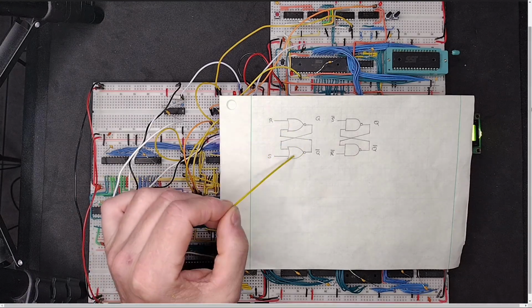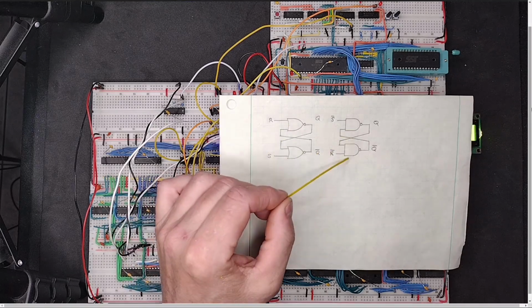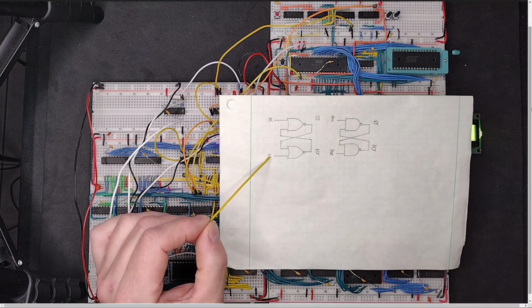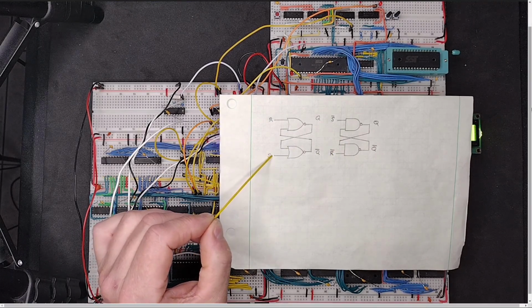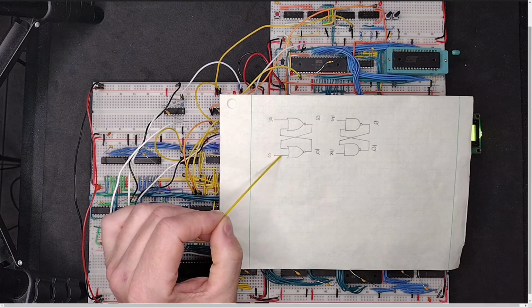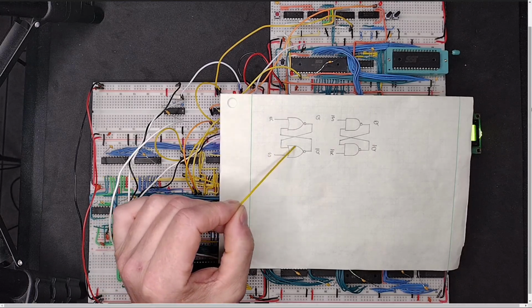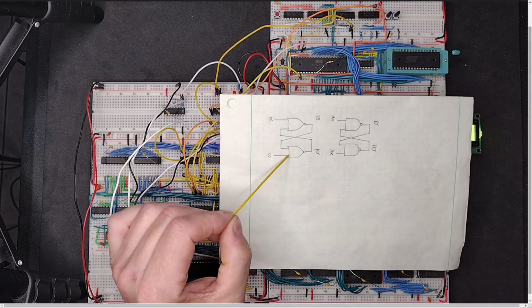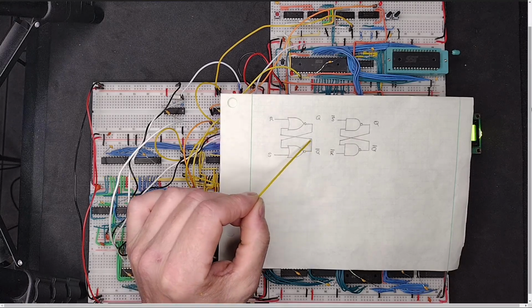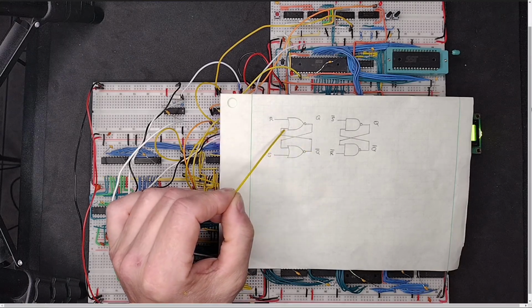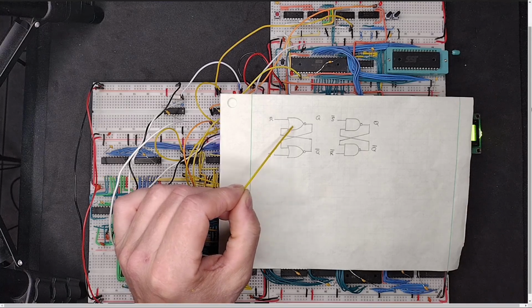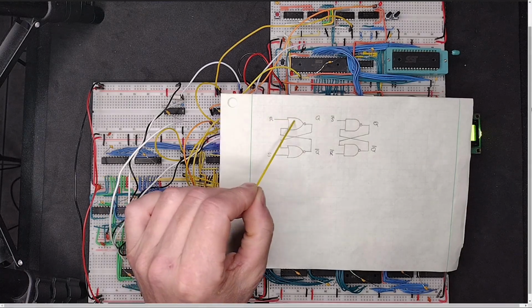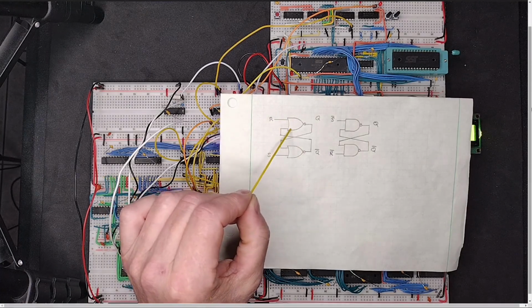And there's two types. There's types that you can build with a NOR gate, and there's types you can build with a NAND gate. If you use a pair of NOR gates, then a positive signal on the S line, the set line, that's what the S stands for, set, and the R for reset. So a positive signal on the set line will cause the NOR gate's output to go low, because one or more of the input signals is high. And that'll cause the input on this other gate to be low. And if R is currently being held low, which is the normal state for this type of flip-flop, then both of these inputs are low.